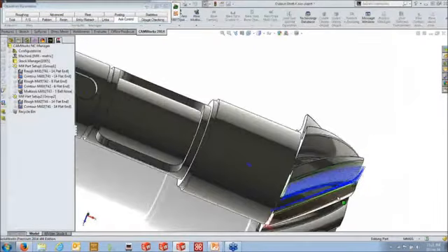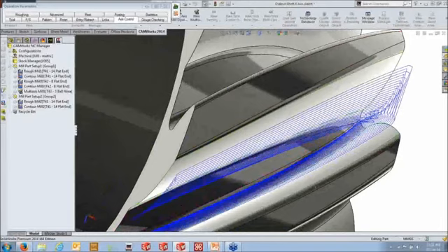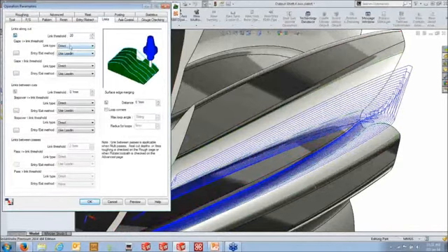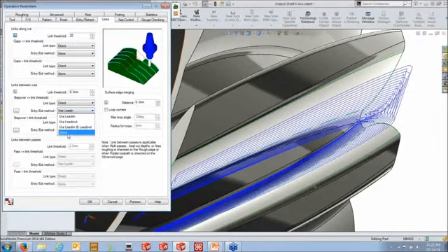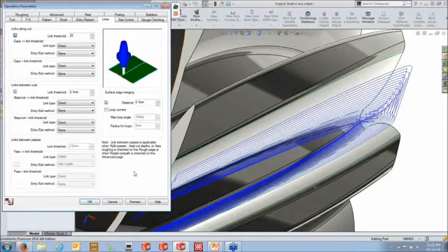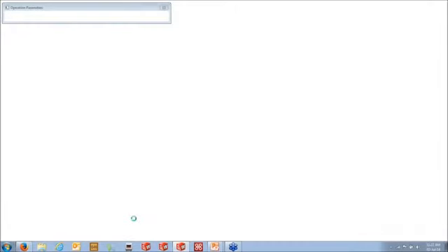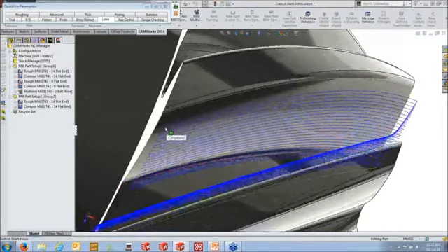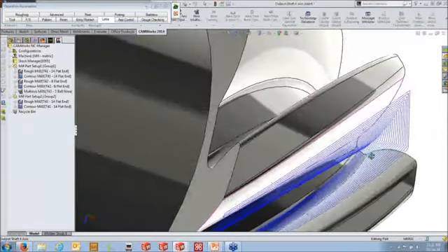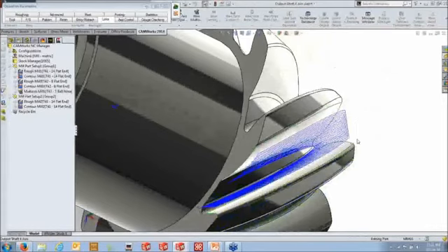So it looks like it just generated there for me. Now it looks like we've also got some lead-ins, so I might just go into my links tab up here, and some of my default settings here are set to use a lead-in on every single pass, so we'll just remove some of those. To preview, just update, make sure we get these disappeared from it. So that clears up the end options right here. So that's almost like a finished pass apart from our allowance. But this is essentially the way the area roughing tool works.